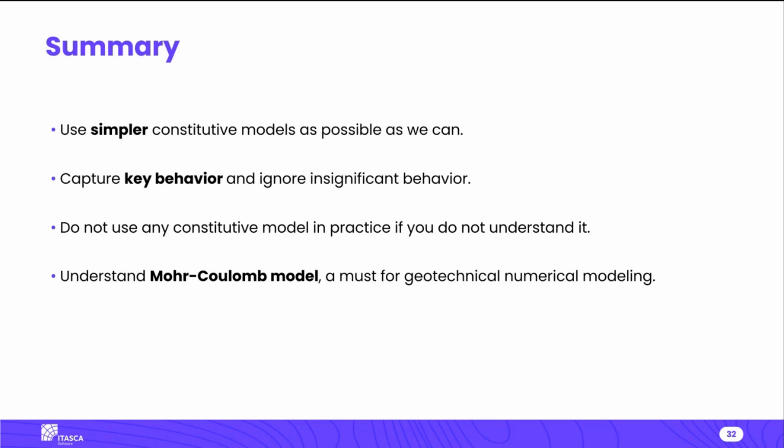Understand the Mohr-Coulomb model. Pretty much all the models that we use in rocks are based on the Mohr-Coulomb model. Not necessarily true in soils, but in rocks it certainly is. And it's easy to understand, and you should be very familiar with that.